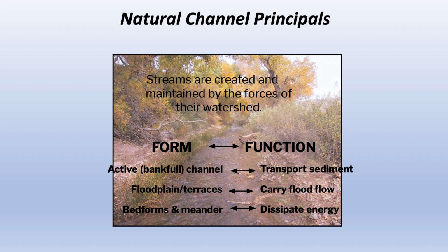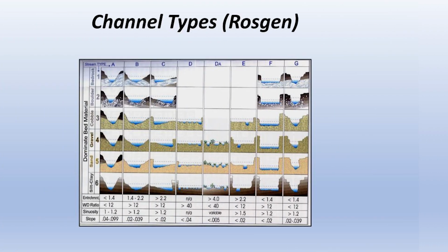So we're looking at the active channel for sediment transport. We're looking at floodplain terraces to carry the high energy of those high flows. And we're looking at the bed forms and meanders as a way to dissipate energy. That's part of that natural channel design principle, and it's part of what goes into this assessment. But it's a visual assessment, so you can do it quite rapidly with a trained eye.